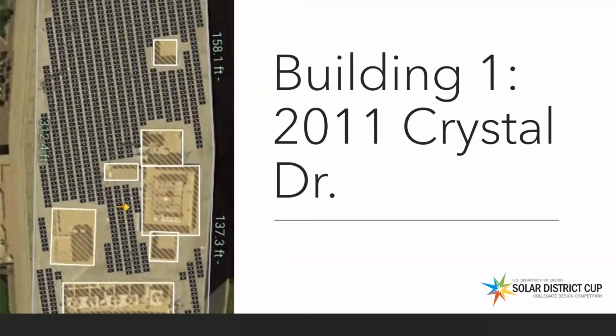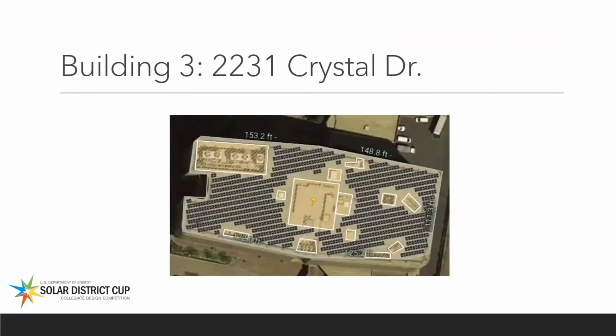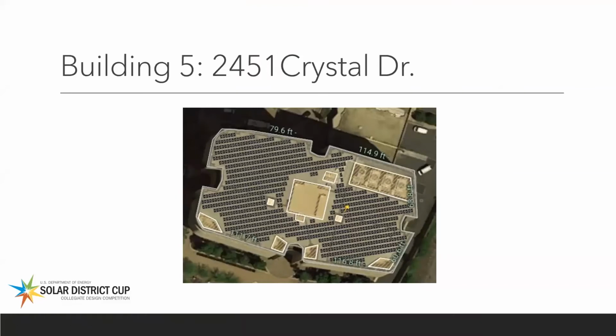Each building, as you're going to see scrolling across, has its 3-foot exclusion zones all the way around. The HVAC areas have been completely cleared of solar panels, as well as the row spacing, to allow maintenance crews to go in and out to fix the panels as necessary.